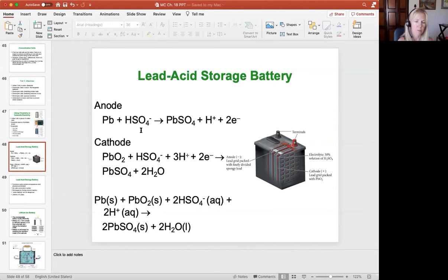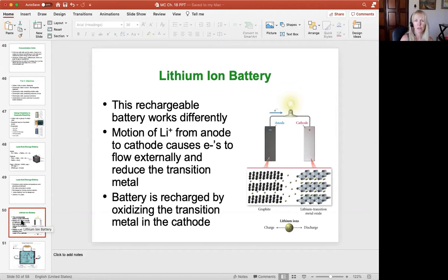When you jumpstart a battery, it used to be more of a problem, but now the way that they're making the new batteries is they're a little bit more contained, and so you don't have leaks and stuff. But if you have a leak in your battery, that's a really dangerous situation, because this sulfuric acid can aerosolize, so you have to be really careful, especially if you're going to jump start a car. You just want to inspect that battery to make sure there aren't any cracks or anything like that in it.